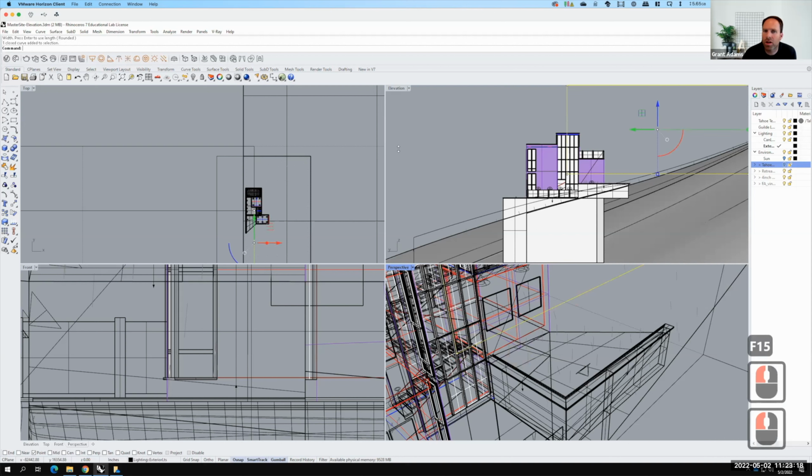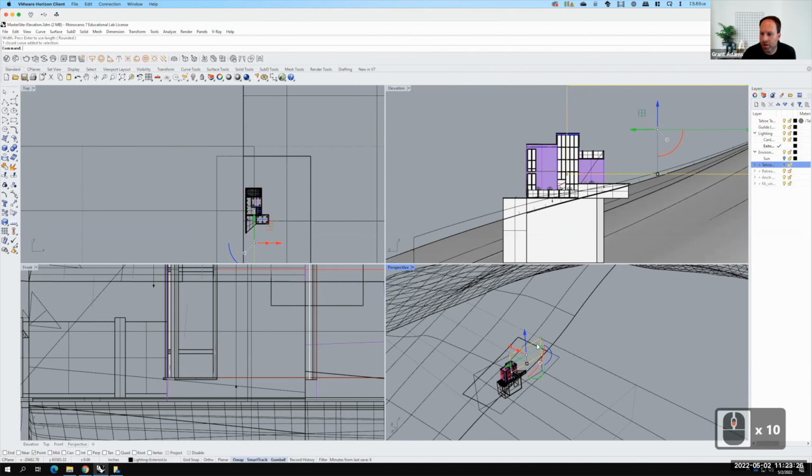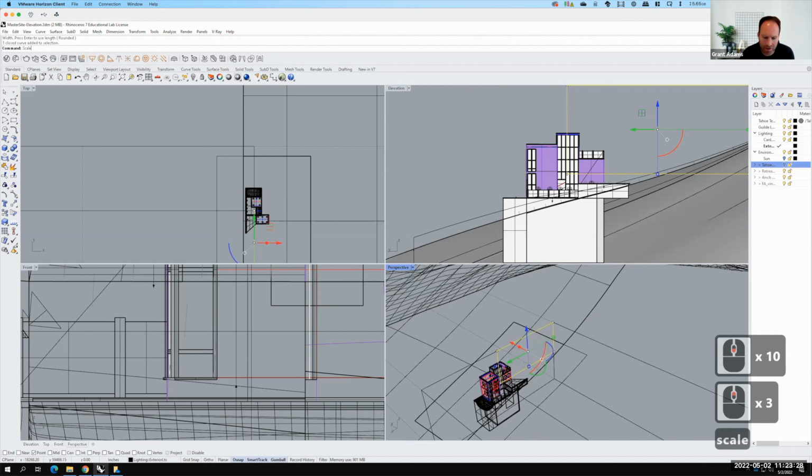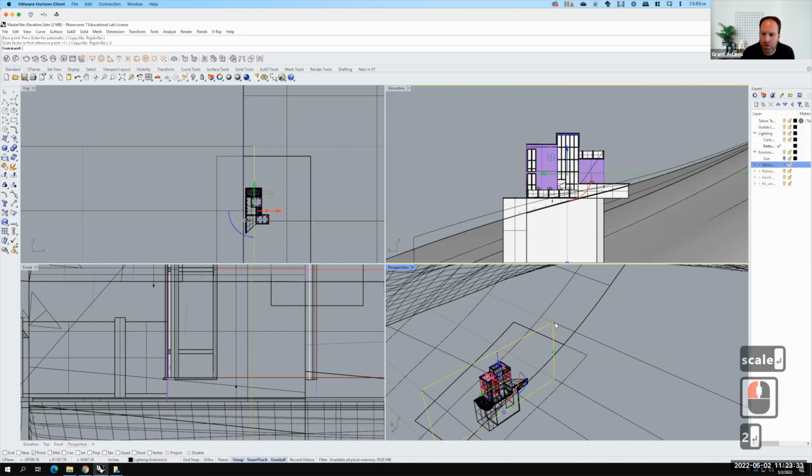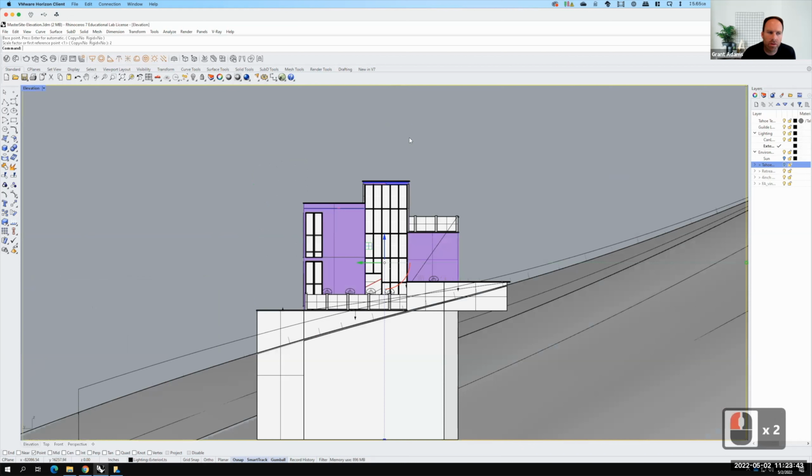And if we look in my elevation view, notice that rectangle is exactly a quarter of my overall view. So if I were to scale that up by 2, if I said scale, and I chose this corner as my point, and I typed in 2, that rectangle would be exactly the same size as my viewport. And that's what I want. So let's go back and make the elevation view the full size. There it is. And let's go ahead and do a make 2D command.